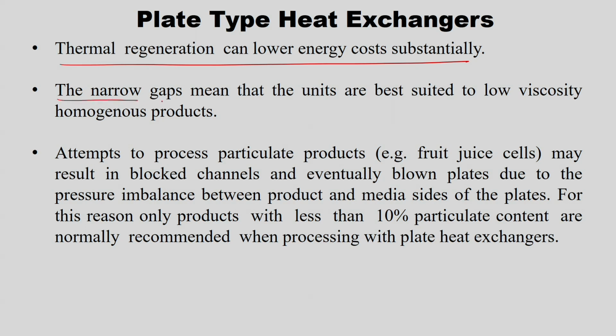The narrow gaps mean that the units are best suited for low viscosity homogeneous products, because the gaps between the plates are very narrow. So, we cannot handle liquid food with a large amount of particulate solids, because it gets in between the plates and further fouling can occur.